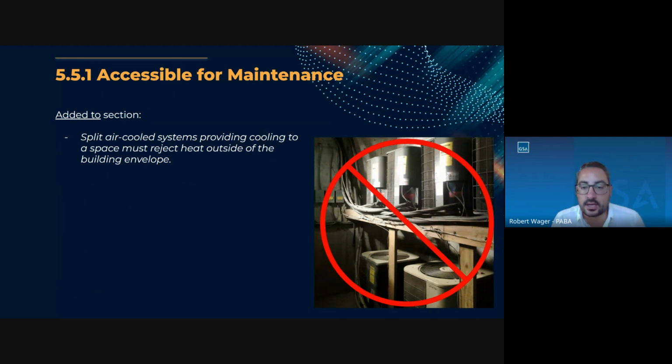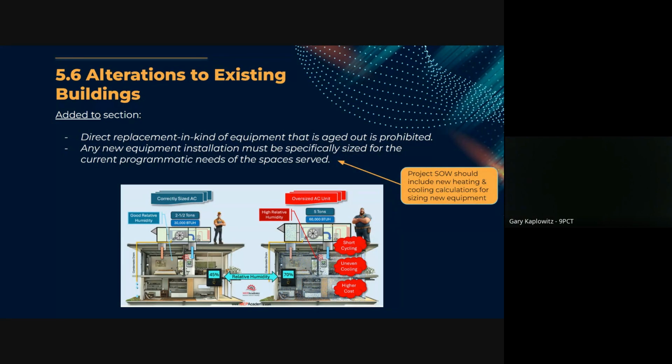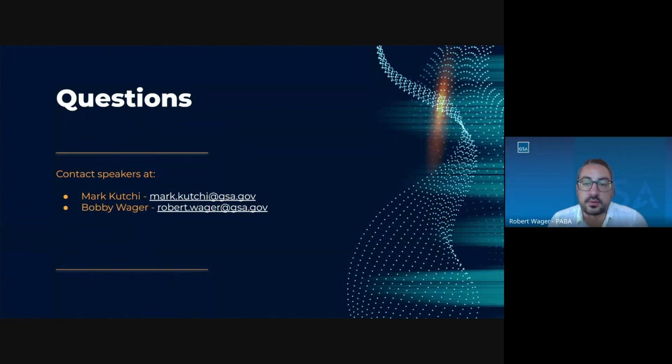Even if you have a mechanical space that has exhaust fans that can introduce an air change, if it's meant to be outside, it should be outside. So does that apply if we have a louvered outdoor air intake or the mechanical rooms on the perimeter? And yeah, I would still say, Gary, if it's located inside the building envelope, it needs to be ducted to the outdoors,